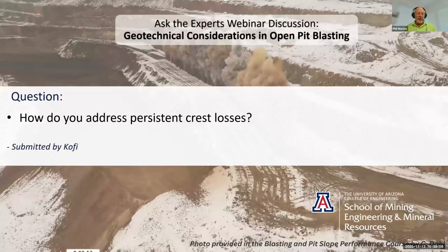And when you get persistent crest loss, there's only two things that are doing it. It's geology and it's energy that's coming from the blast adjacent to that crest. So the key thing here, again, we keep coming back to vibration. If you don't do any monitoring of what's happening when you are blasting and having a look at the PPVs that exist at the crests or just behind them versus what you're modeling or what your intention is, and the critical PPV for the rock mass that you're in, you can never improve.